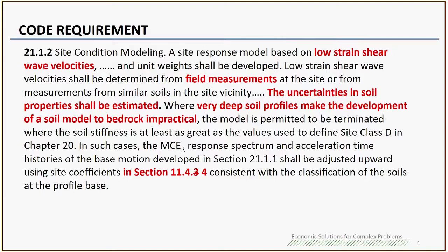situation is, for example, if you have a very deep soil site, you cannot drill a hole into the bedrock. Then the code allows you to terminate the soil stiffness at the site class D, defined in Chapter 20. And then you need to develop the input motion based on the site class D spectrum.